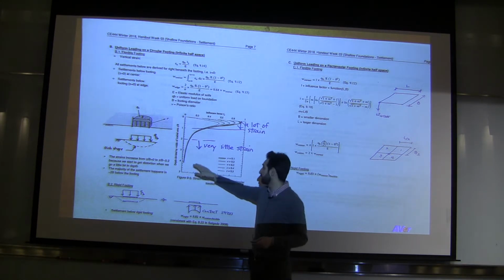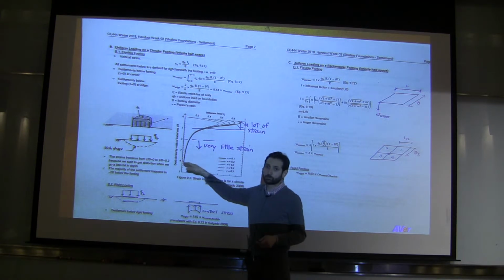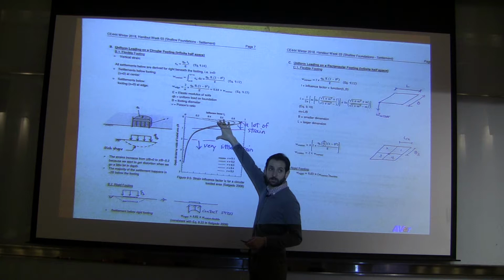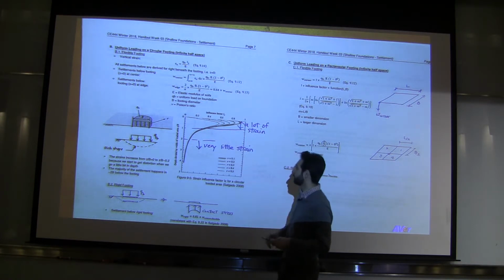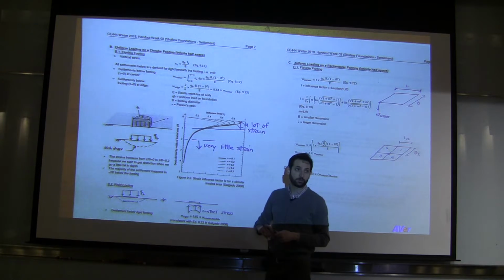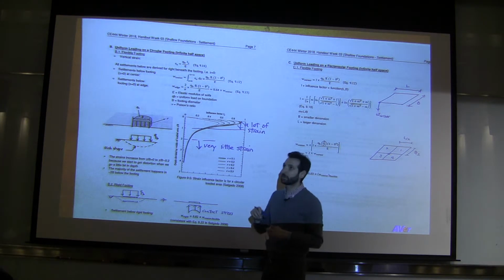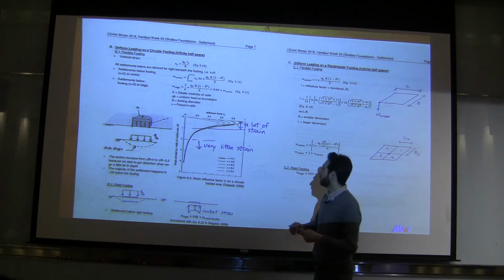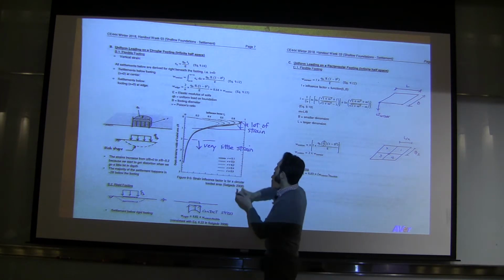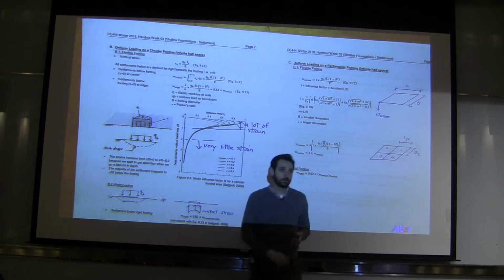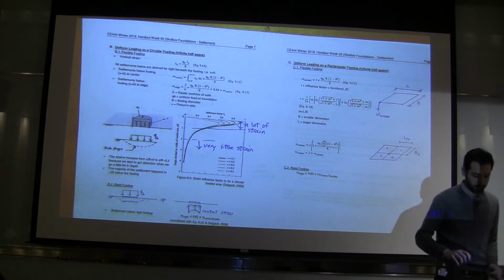You don't really care if it's soft or strong soil down here. What you really care about is what is right there. And that's 2 times foundation depth, 2 times foundation dimension. And most of the strain occurs right here, so about one foundation dimension.